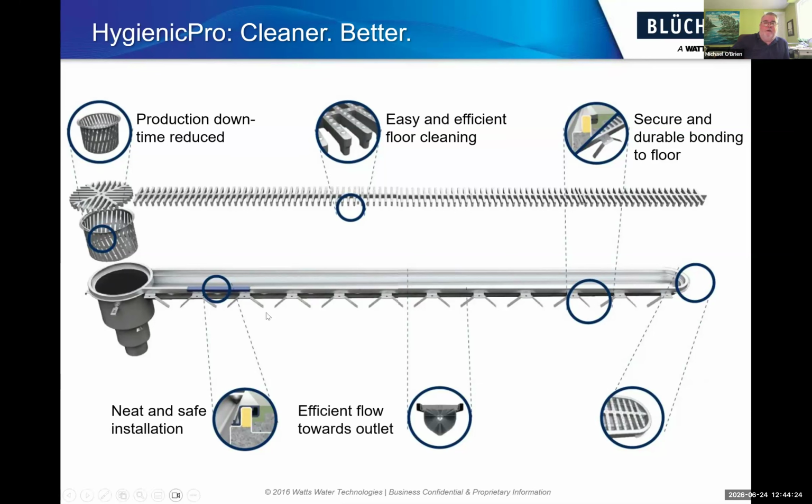Next thing is the flow on this particular channel is specifically designed in a rounded off V type of shape. So as solids come across and drop in, they tend to settle down in the center where they're easier to clean out. And because of the pinch shape here, any given volume of water will have a higher velocity through the channel, and the velocity is what carries the solids down.